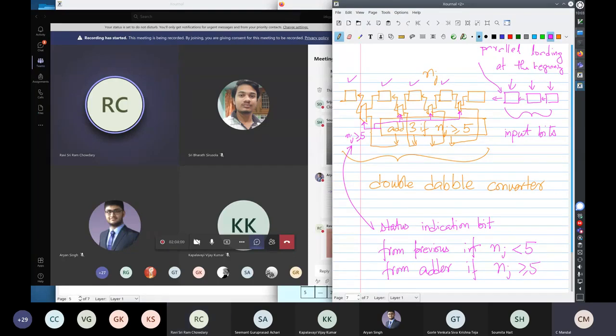Actually, you can also do it using a finite state machine controller. You can do it manually, but that's fine. But you can also design a controller, because after all that's an FSM. So at the very beginning, you will load it, and in the subsequent states you will just keep on shifting. That could be a simple finite state machine.